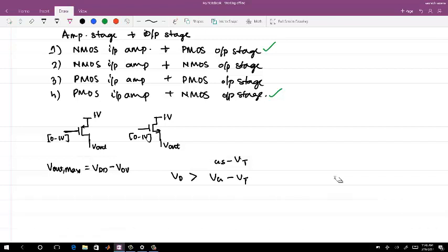The easier way to work this out is to forget the equations right now. You need a certain VD sat equal to the V overdrive, right? If you maintain your VDS equal to VD sat, then if VDD is 1 volt, your V out can be 1 minus V overdrive, and I'm just finding the minimum gate voltage for that. So what should be the minimum gate voltage?